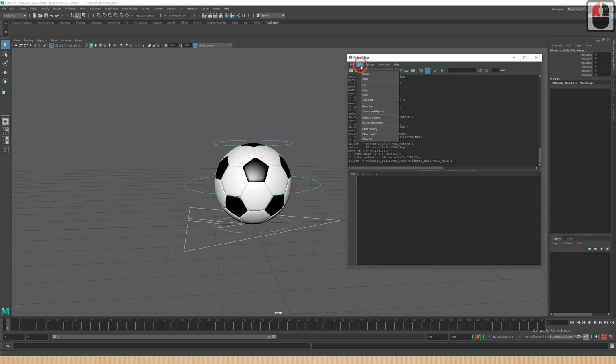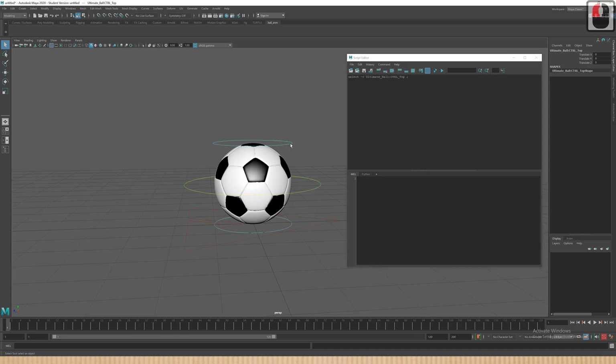So what I will do is edit. I'm going to clear all so that it's totally clean. First, I'll select the controllers for animating. I'll go from the top to the bottom. So first press this controller, press your shift button. All the shortcuts, whatever I'm doing, will be mirrored on the top right corner. So just press shift and your left mouse button. Without leaving it, one more click. So you'll be able to select all the three controllers here.